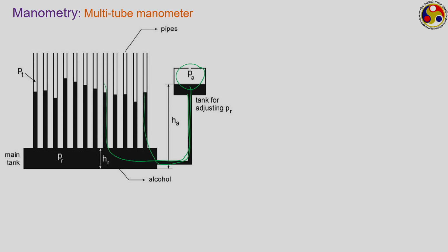Like suppose you are expecting rapid variation in pressure in some channel, something like a shock tube. There we need an idea about the pressure value at very small distances apart, and there we can easily mount such multiple manometers or multi-tube manometers.